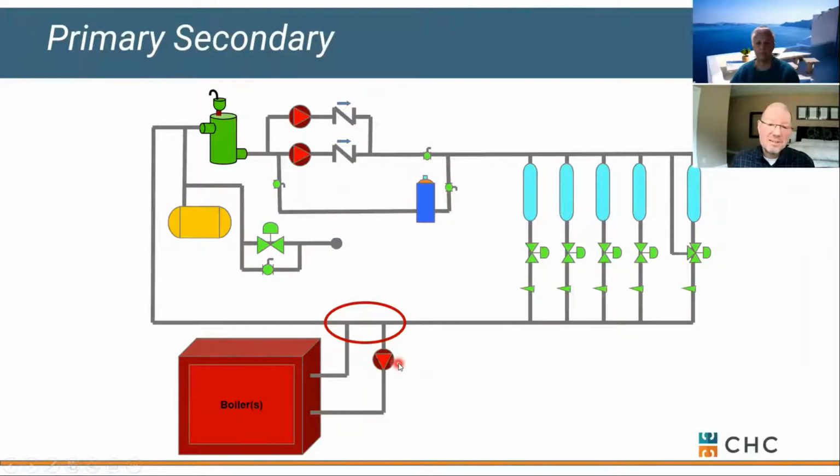This pump for the boiler in this case is simply sized for the piping between this T through the boiler, any pressure drop through the boiler, and back to this T. So this tends to be a fairly small pump. Very easy to troubleshoot, okay? That's a standard primary secondary system. Remember, closely spaced T's, dedicated pump.